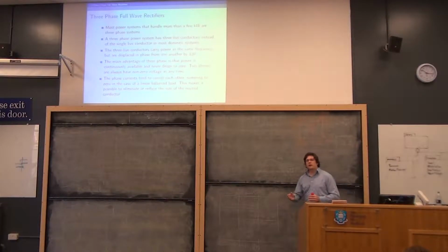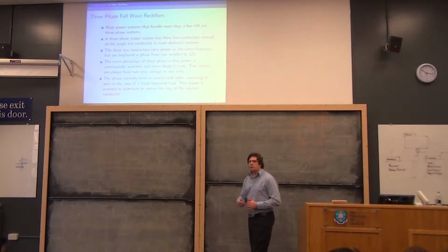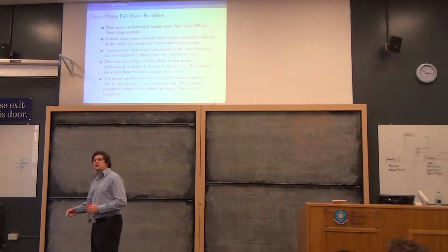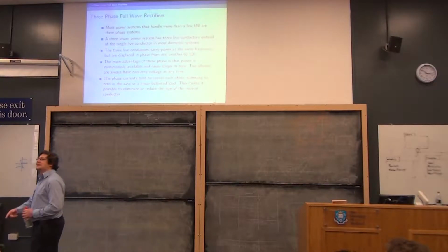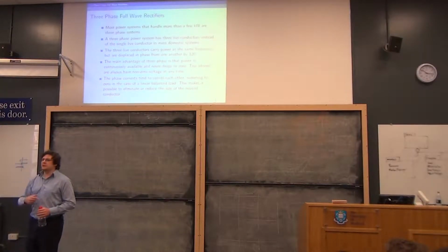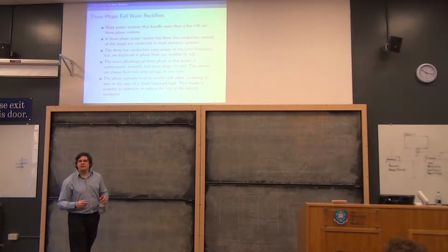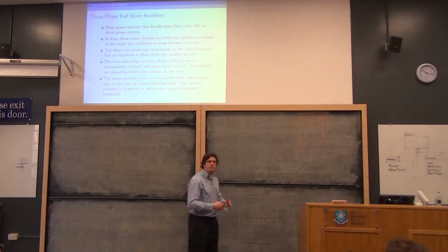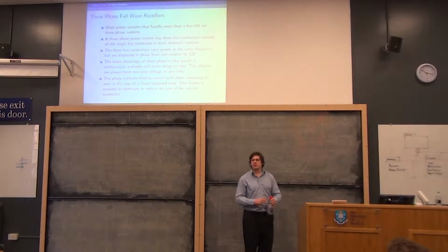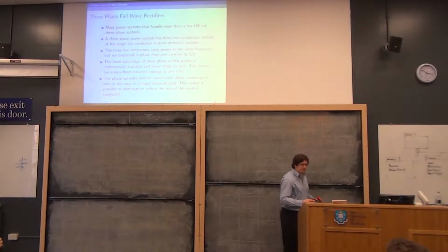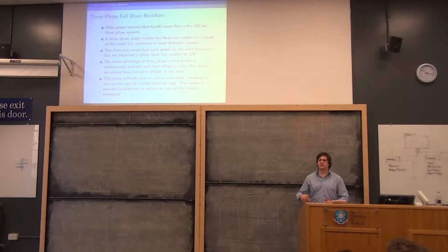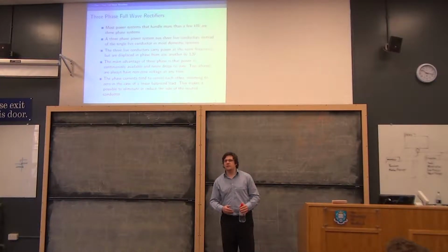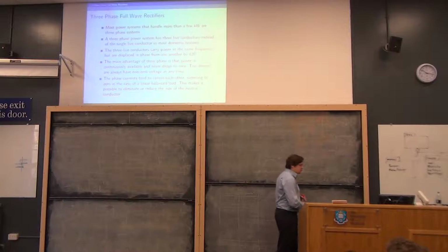So the way a street is usually wired up is house number 1 will be on grey, and house number 2 will be on brown, and house number 3 will be on the other new colour, which I can't remember what it is, black. And then house number 4 will be back on grey again. And the logic is that, generally speaking, the load will be the same in each house. So if it's evening, people come home broadly at the same time. Let's assume that nobody works night shift in this. And the load will go up because they come home, they want to cook dinner and watch the telly and do whatever else they do in their free time. So collectively, all the houses will take more, and at night, they'll all take less. So overall, there's balance across the phases.